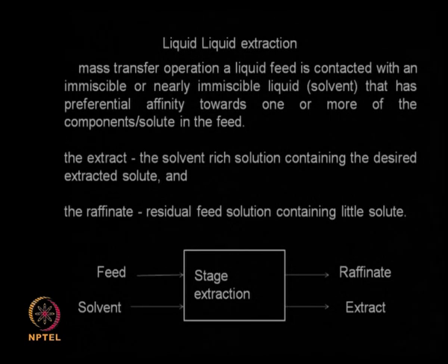You use a solvent, the solvent is immiscible or very sparingly miscible, and this solvent will extract preferentially the solute of your interest. You cannot say that only one solute will get extracted, because after the end of the fermentation broth you may have a large number of metabolites, so you may have some of the unwanted metabolites also getting extracted, but that is possible.